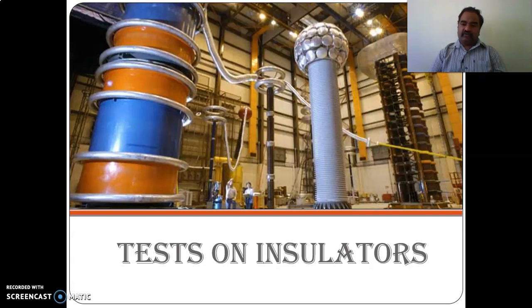We are on to unit number 4, which deals with testing of equipment that are used in high voltage engineering. As we see, the different equipment that are commonly employed to withstand high voltages are, the first one being the insulators, overhead insulators. The second one, the transformers and the bushings. The third one being the isolators and the circuit breakers. Number 4 being the surge diverters. And number 5 being the cables. So all these 5 equipment are there in your syllabus in your unit number 4. So we will see the different tests that are conducted on these equipment before bringing them into field.